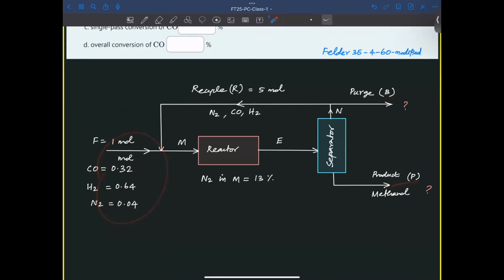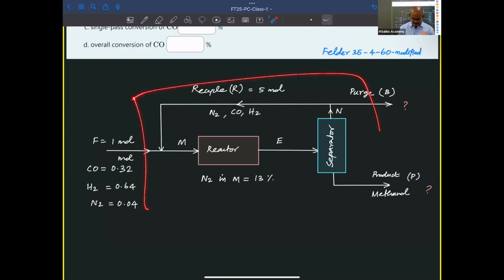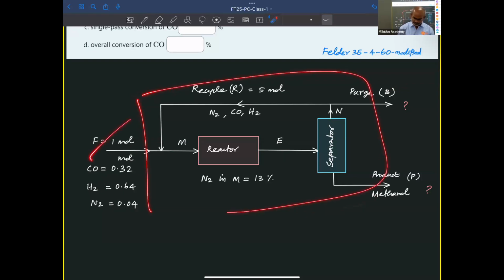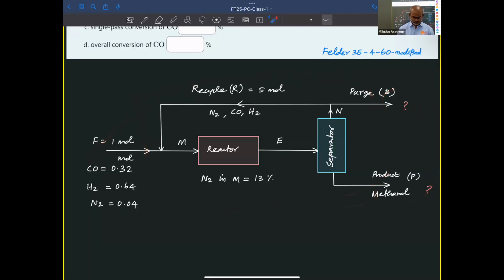But if it starts to accumulate, then it will be unsteady, no, sir? Unsteady state we don't allow that condition. It is simply whatever is entering has to leave. So nitrogen entering is nitrogen leaving, hydrogen entering is hydrogen leaving. In terms of atoms, all the C entering has to leave. So it is an atom balance. No need to concentrate on the unsteady state condition.